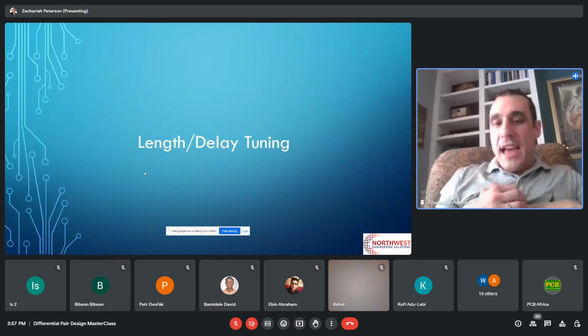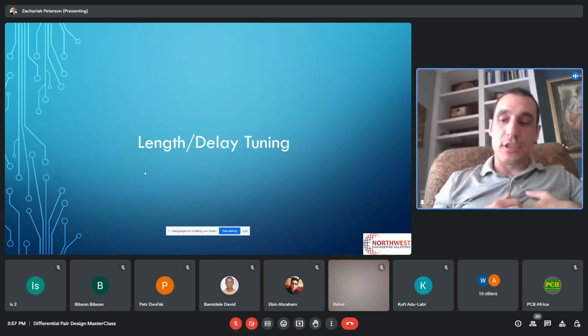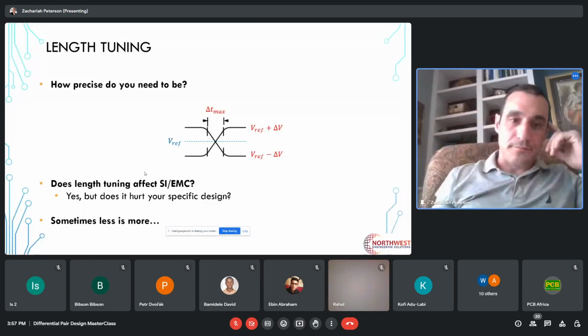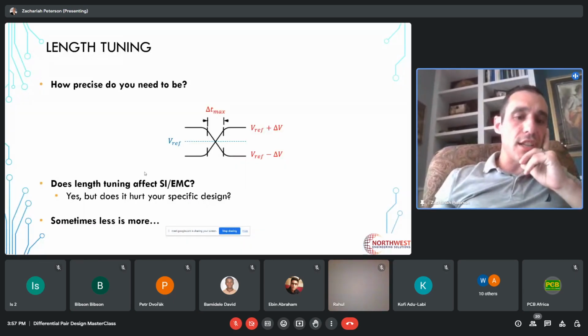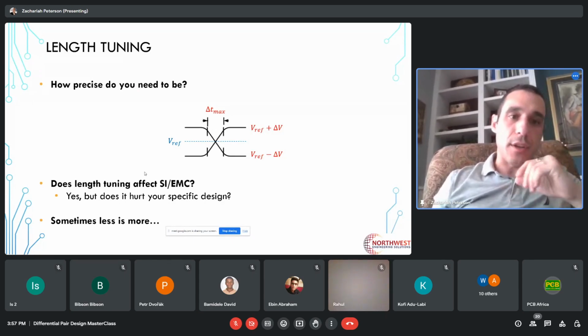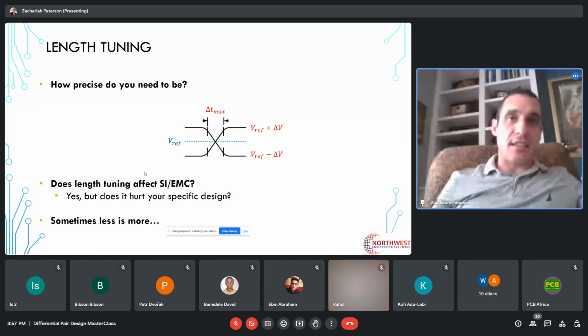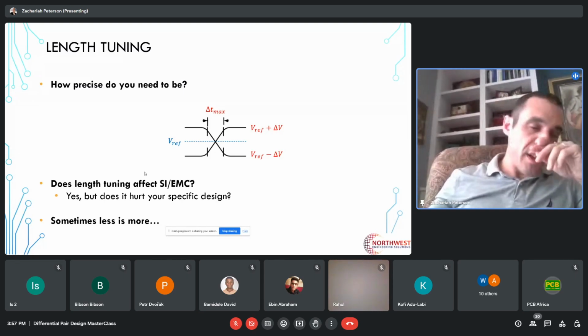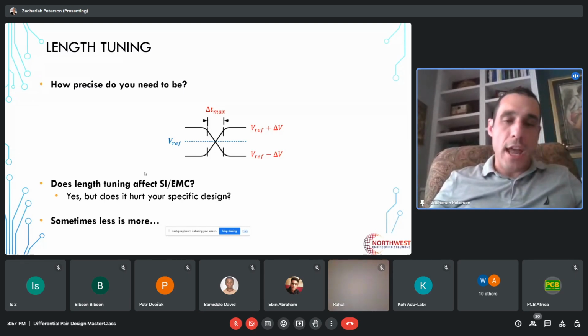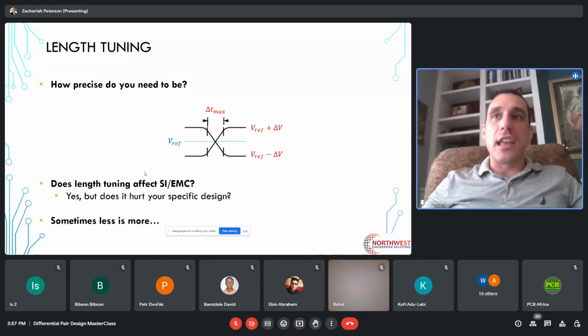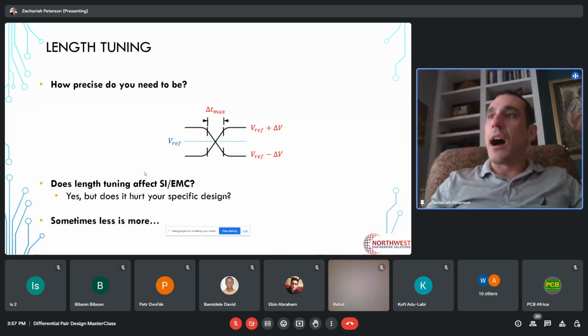Okay, next, I want to talk about length or delay tuning, really the same thing. We already talked a little bit about length tuning and delay tuning, and I mentioned that it's a very good idea, for reasons of accounting for skew overhead, to have the signals lined up with each other in time as close as possible. And that generally means that they need to be the same length.